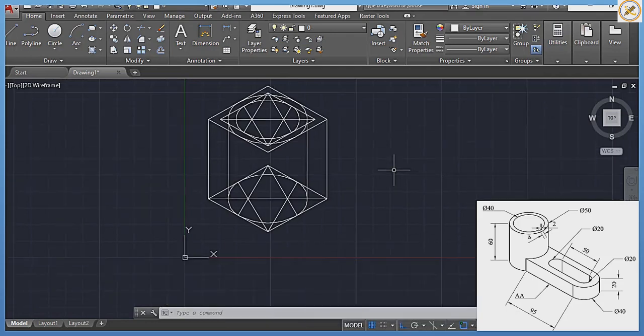Okay, so doing the second part right now. We see that towards our bottom right hand side, the diameter of the cylindrical part there is diameter 40. Applying the principle of isometric curve, 95, half of 40 is 20. So 95 plus 20, that's 115.